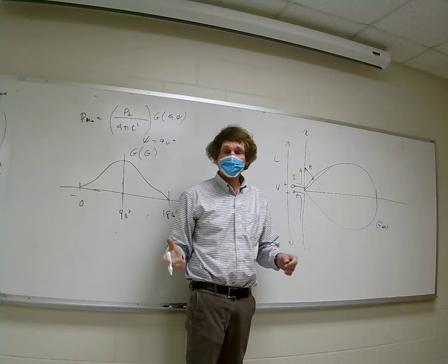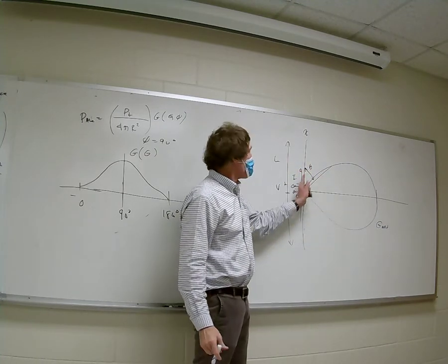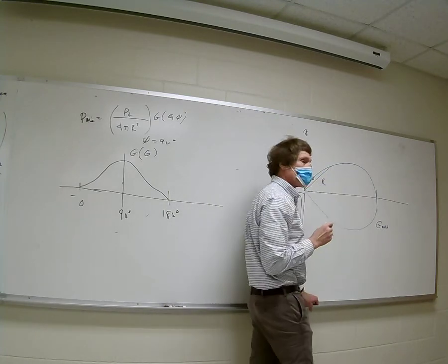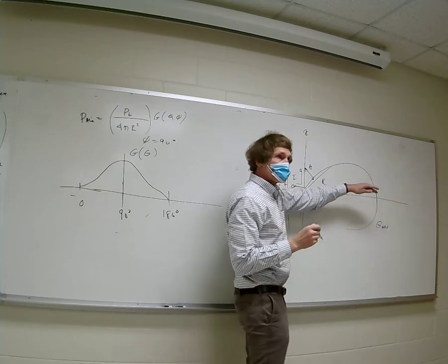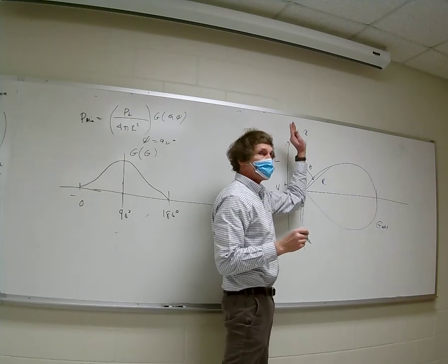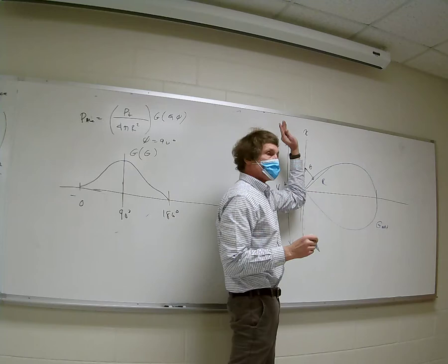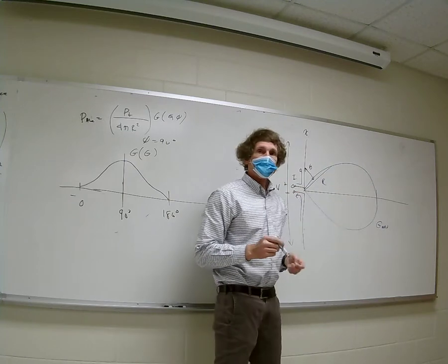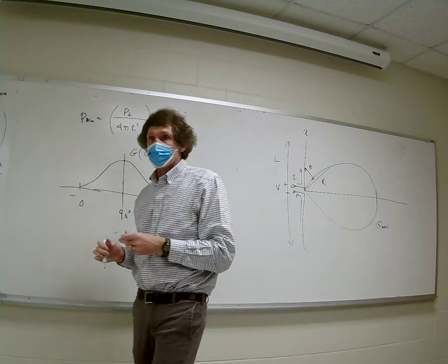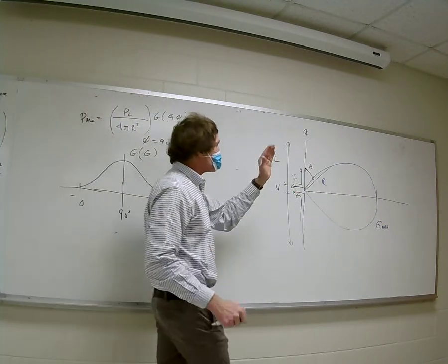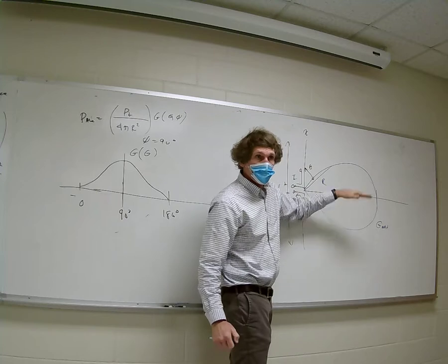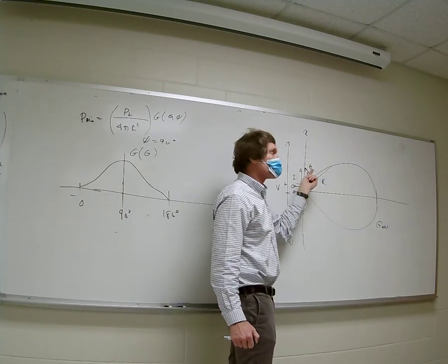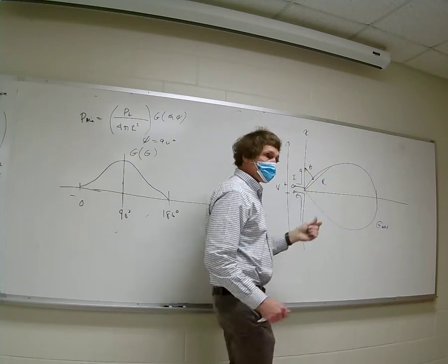Do y'all follow me on this? So here it's versus angle theta, and the length of this vector r is proportional to the gain. So the gain's max out here. Do y'all follow me? It's like a wiper arm, a variable length. Right up the axis of the antenna, it's got nothing, and it starts getting better and better and better. And when I'm coming out perpendicularly, it's going to be a maximum value. That's a typical kind of antenna pattern. Here I'm showing it versus spherical angle. Do y'all follow me on this? It's a spherical type of thing. You might say the length of the arm is proportional to the gain at a given angle.